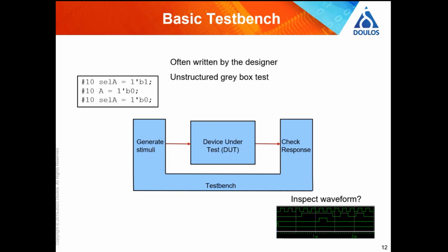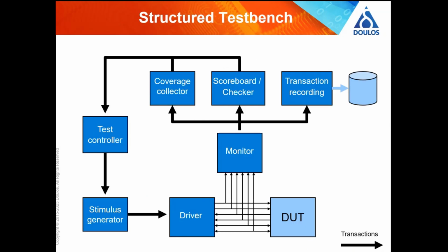But the disadvantage, of many disadvantages, but a key disadvantage of this kind of test bench: quick to write, quick and dirty, very hard to maintain. You make some small change, and the output that was supposed to come out at time 1, 2, 3, 4, 5 suddenly comes out at time 1, 2, 3, 4, 7, and your test fails, and you've got to constantly edit your code to keep it up to date. Whereas if you have what is called a structured test bench, you're going to find this better in many ways, including the problem that I've just mentioned, keeping the test bench maintained.